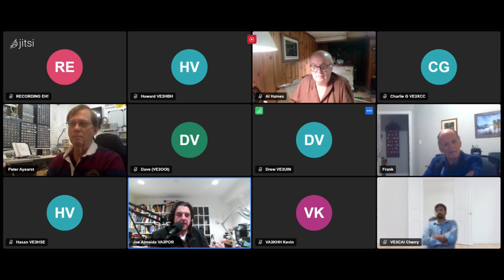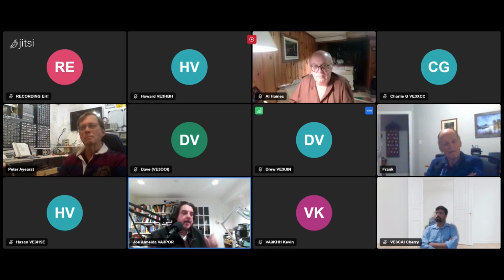So a little bit of testing on the bench, and I realized that one of the filters, it was the 10 meter band filter, which all the other bands go through. It wasn't allowing signal to go through. So I had to resolder that up, and I was able to get signal through. And then I checked all the other filters the same way, and I was able to get signal through.